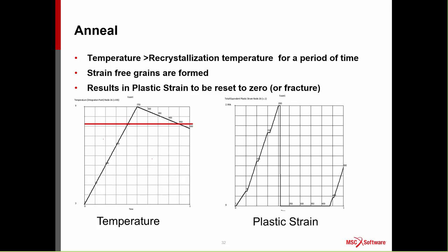Here what we do is we say the annealing is really a material characteristic, and if we had done both loading and temperature, we would have had our material undergoing increased loading, and there were some hold periods in here, but we would generate a certain amount of permanent plastic strain.